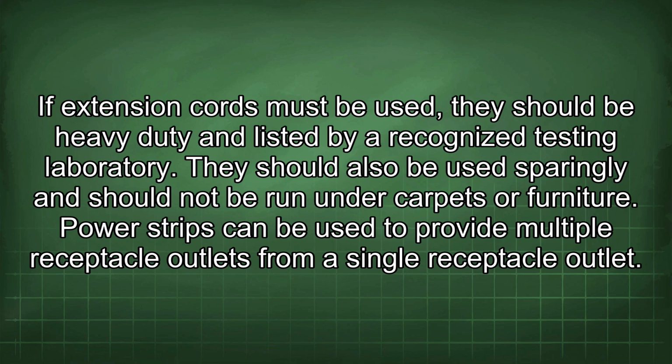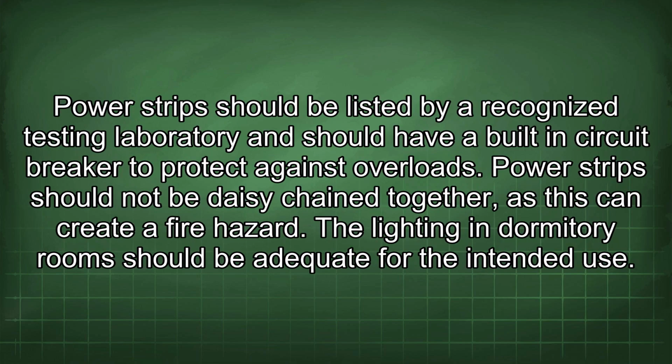Power strips can be used to provide multiple receptacle outlets from a single receptacle outlet. Power strips should be listed by a recognized testing laboratory and should have a built-in circuit breaker to protect against overloads. Power strips should not be daisy-chained together, as this can create a fire hazard.